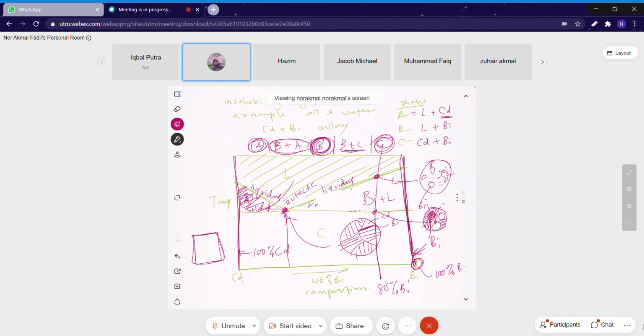If you look at the composition, let's say this is the boundary for the lamellar structure. Whatever your alloy here at this hypereutectic region, it contains a mixture from the left, which is the intermetallic line, and the right is pure bismuth. So you can have this kind of microstructure. Okay, hypo and hyper.